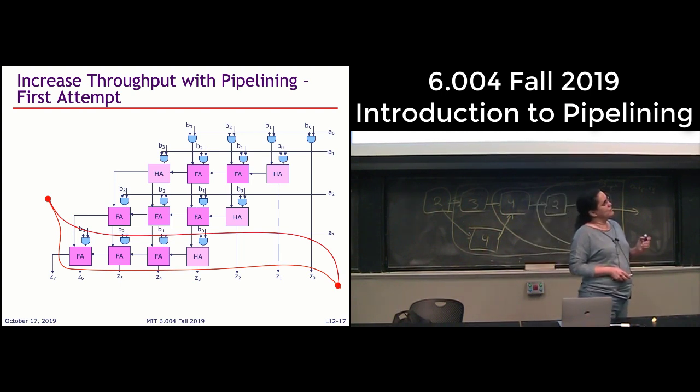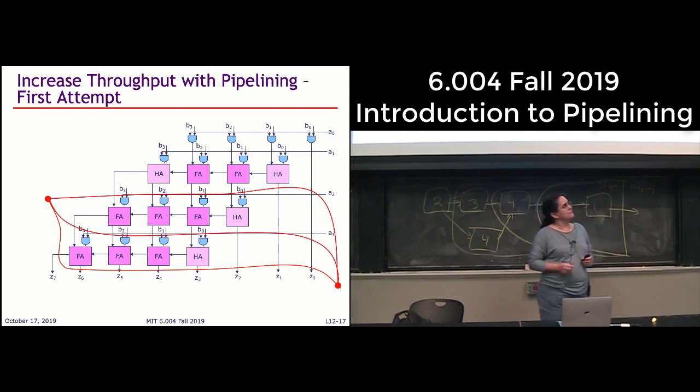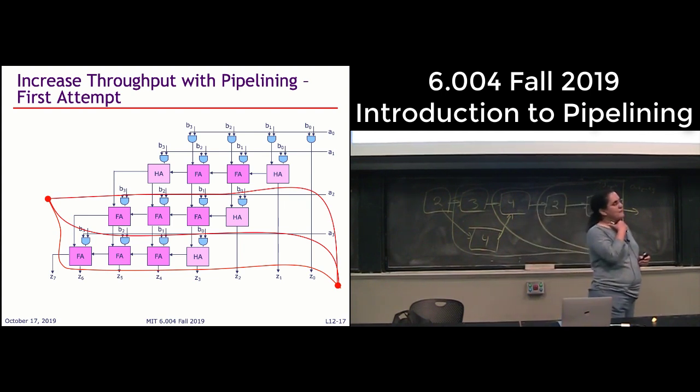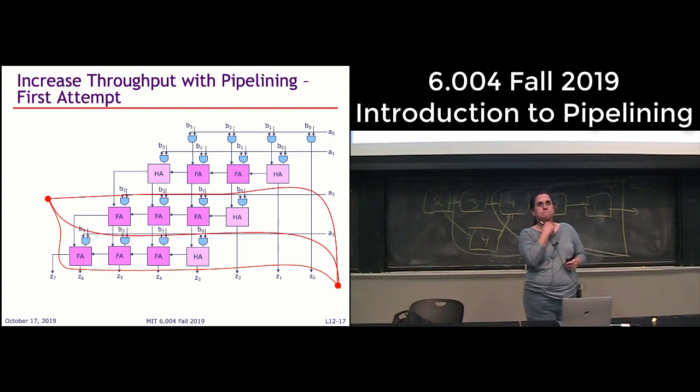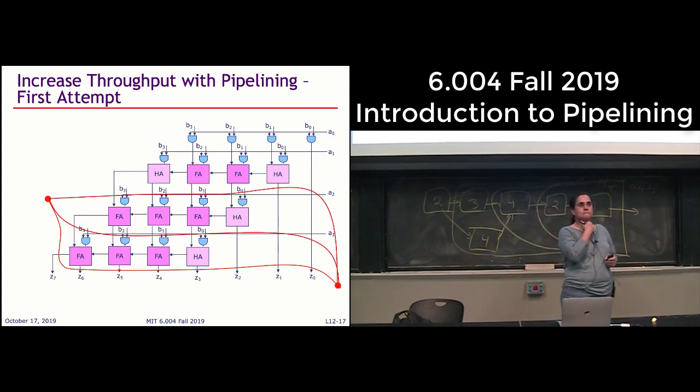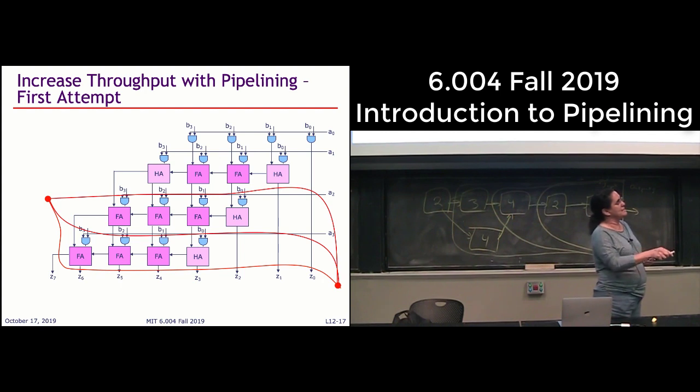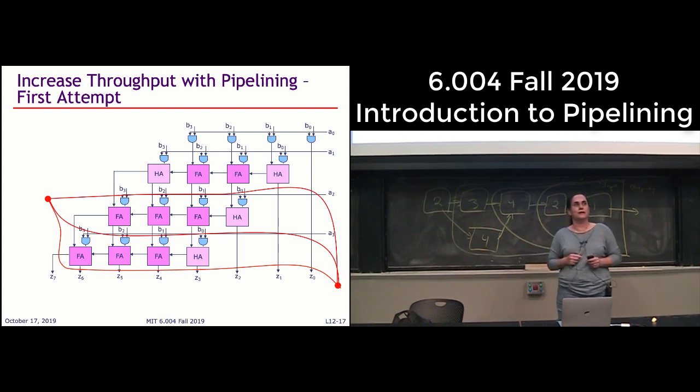And then I draw another contour, and so on, okay? So what do we think of this pipeline circuit? Is it a valid pipeline circuit? It is, because if I go from every input to output, I always have these, right now, 3 registers or 3 contours that I'm crossing.